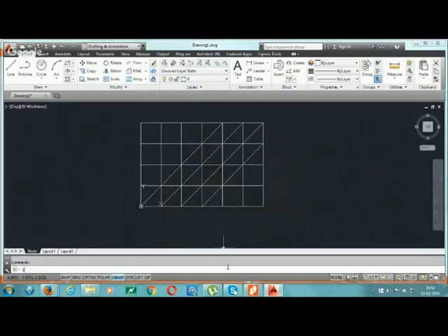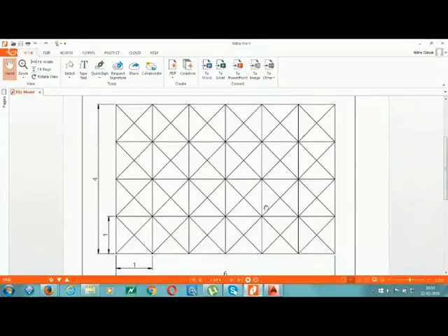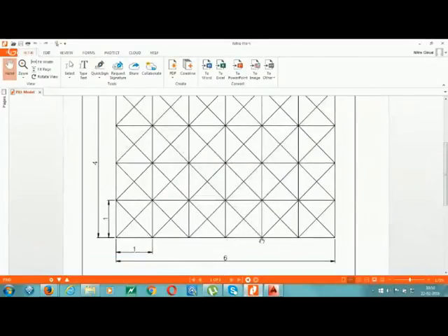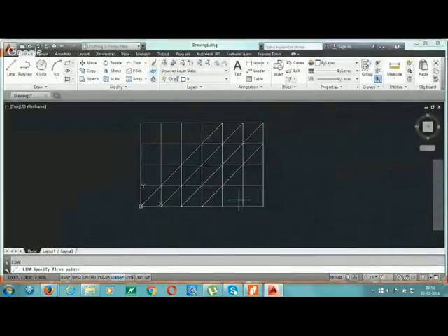Now go to the line command. In the diagram, we can see we made this line. So select this line's endpoint and select the other endpoint. Escape. Again, take the line command, start at this endpoint and this one. With the help of OSnap, we complete our diagram.